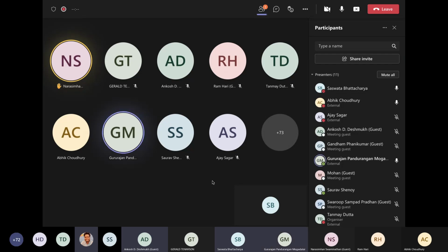But Shashwat, still that uniqueness, that I give you the composition and volume fraction, and so what is the phase diagram, that still breaks down. Yes, that breaks down. That is the problem. One system will not have one single energy. No, it has multiple energies. Exactly. It will have multiple energies depending on the shape. Yes, exactly. So the lever rule breaks down. That's what Johnson wrote, right? So you can't construct the phase diagram properly.